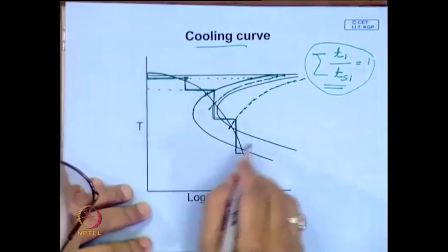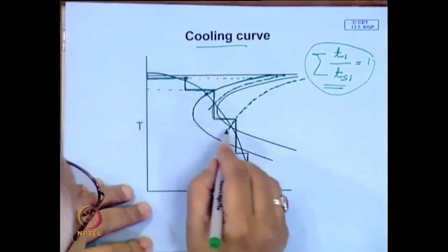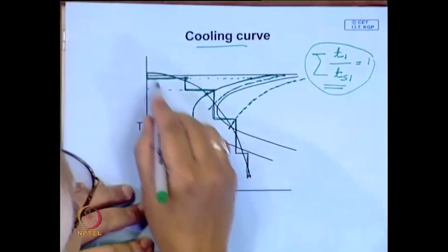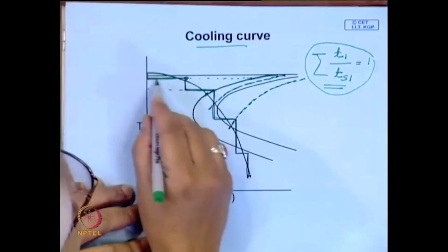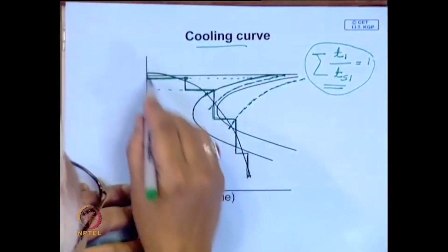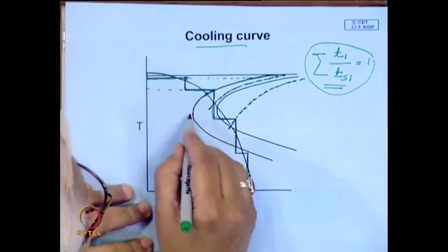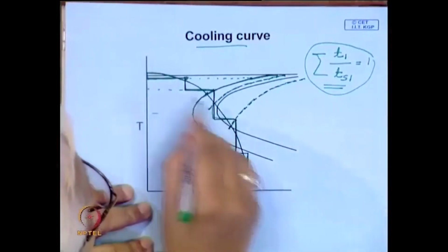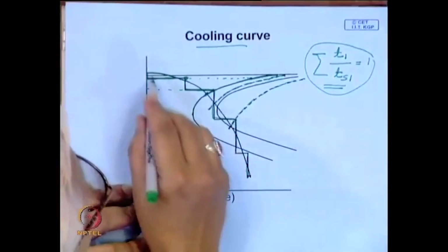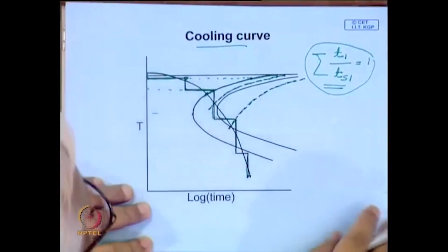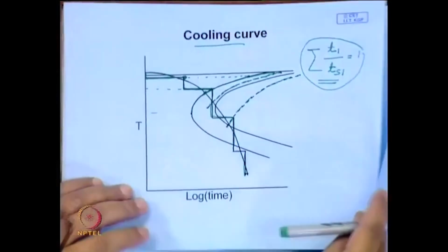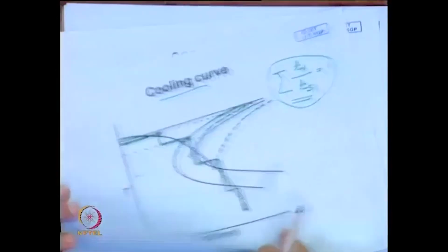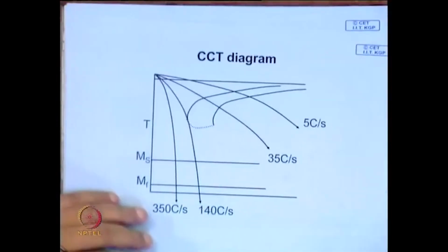It is also extremely difficult, in plain carbon steel, for bainitic transformation to take place unless you cool it isothermally below the nose. So, this is a problem. Therefore, in most plain carbon steel, if you look at the CCT diagram, you will find the diagrams are like this.